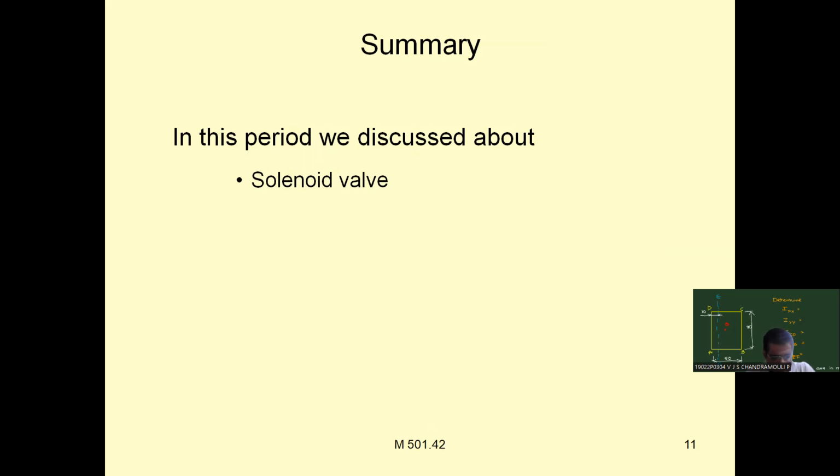Okay, so this dryer ensures the removal of moisture content present in the refrigerant. So the refrigerant should be free of moisture before entering the expansion valve. As the temperature is reduced, any moisture may cause blockage of flow inside the expansion device. So that's why any moisture should be removed just before entering the expansion device. For that purpose, these dryers are used.